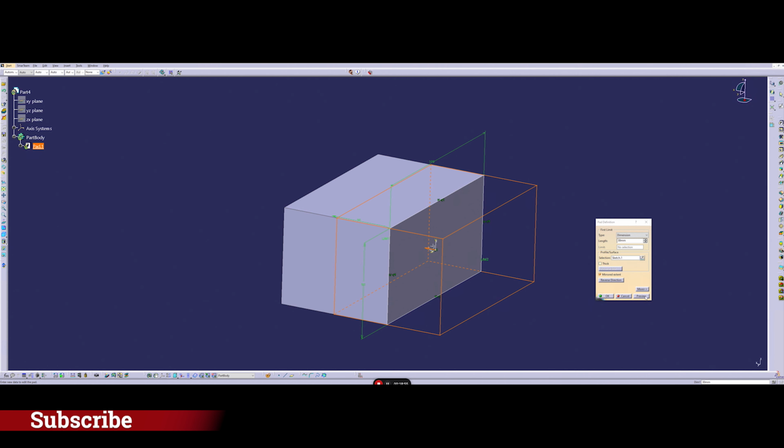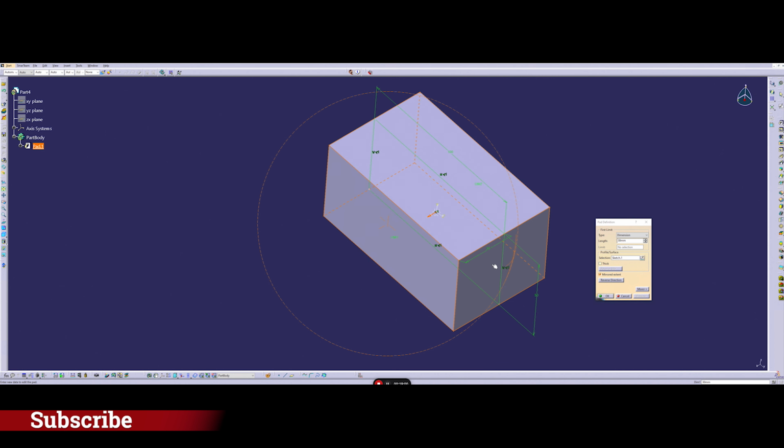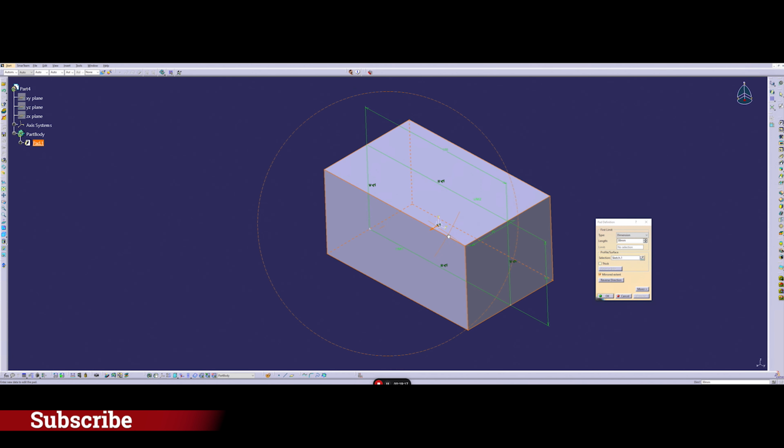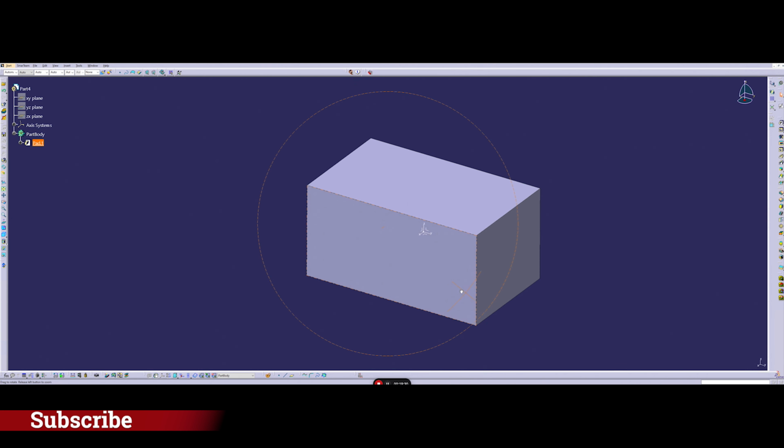So if you do preview, you see that again I have 30 millimeters as the profile length of my part, which is written here, but because it is mirror extend, I have 30 plus 30, so typically it's 60 millimeters width. So if everything is fine, I push OK, and everything is great. So this is how you can create a profile.